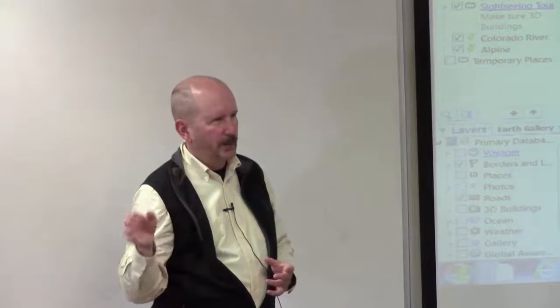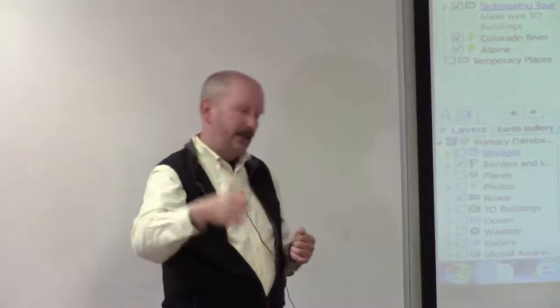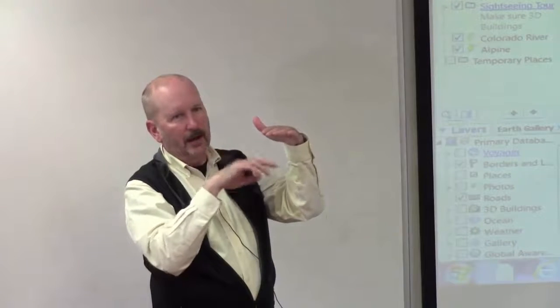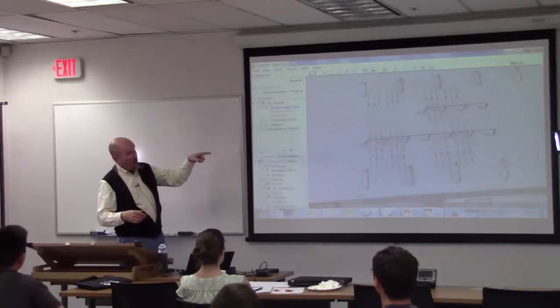So when they took our brand new, nice and galvanized member out there and put it underneath it, it didn't fit. And what we hadn't considered was that we couldn't just use one that was identical to what was out there, because we were putting it in a slightly different situation that none of us accounted for. So what they had to do was take that thing back to the shop, take the top plate off, cut off about 1.5 inches, put it back, put it in, and then it worked. It's an odd thing, but this is the same situation.